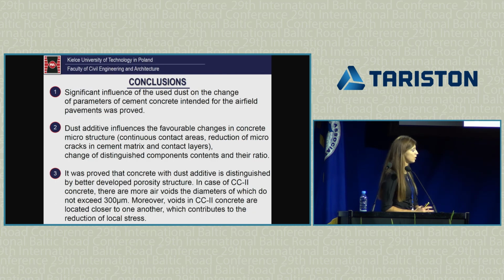After the research, it can be concluded that the significant influence of the used dust on the change of parameters of cement concrete intended for airfield pavements was proved. The dust additive influences a favorable change in concrete microstructure, change of distributed components and their ratio. It was proved that concrete with dust additive has better developed porosity structure in the case of CC2 concrete.